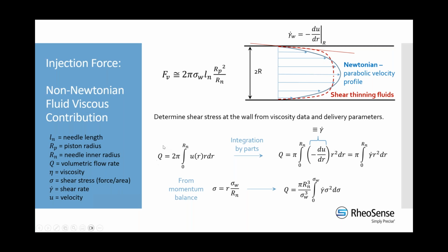Okay, so what I'm starting with is that I can calculate the volumetric flow rate going through my tube or pipe by integrating the velocity profile across the radius. This is very simple. I'm getting this volumetric flow rate by looking at how the flow is across the radius of the tube. An integral is like a sum, so I'm summing up all those fluid elements to get the total volumetric flow rate. Okay, so this still isn't getting us too far. Now we need to get something that we can relate better to our data, because we don't get velocity profiles from our data.